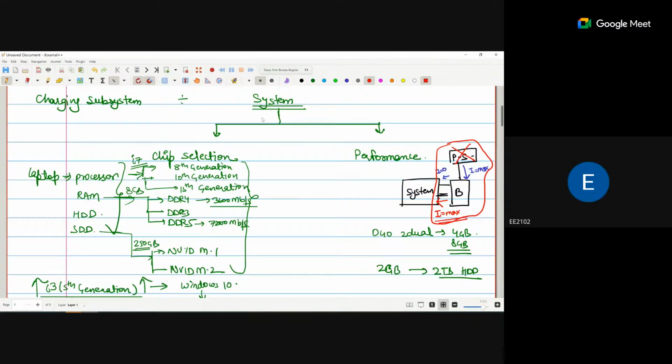For example, with a Bluetooth headset, when you plug in the power supply, the headset stops working. That means the battery is in charging mode, and in this mode it doesn't provide supply to other subsystems.